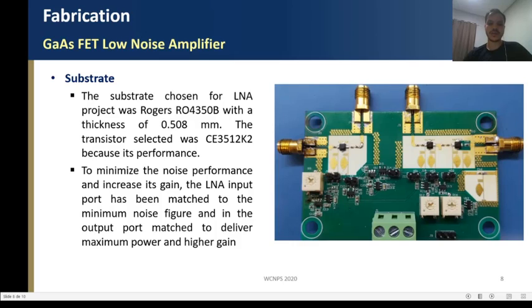Simulations were done in the Keysight Advanced Design System (ADS) with momentum simulation tools. First, a DC analysis was done, and the optimum noise figure and gain performance are achieved with Vg equal to 2 volts and a drain current of 10 mA.